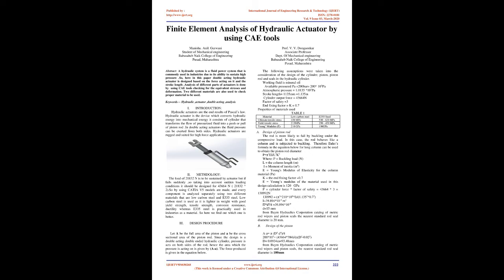Introduction. Hydraulic actuators are the end results of Pascal's law. A hydraulic actuator is the device which converts hydraulic energy into mechanical energy. It consists of a cylinder that transforms the flow of pressurized fluid into a push or pull of the piston rod. In double-acting actuators, the fluid pressure can be exerted from both sides. Hydraulic actuators are rugged and suited for high-force applications.